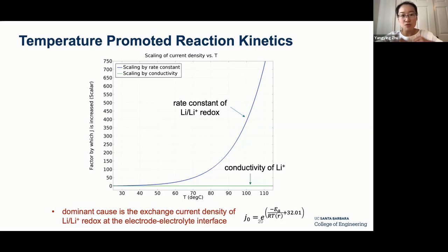And again, you may argue that this is kind of intuitive, because at a higher temperature, you should expect any reactions to occur faster. You wouldn't see this for a uniform temperature battery, because the temperature is the same everywhere. So you still have the uniform deposition. This only occurs when you have a non-uniform temperature. You will see a spatially non-uniform deposition of lithium.